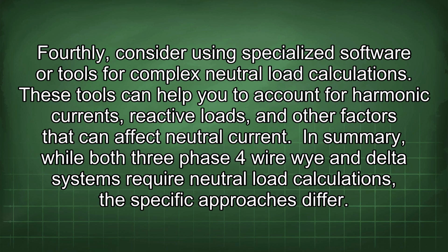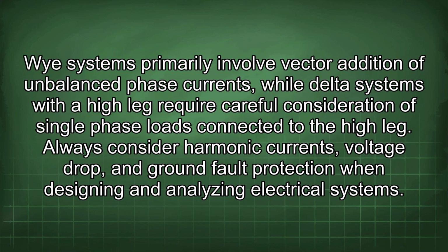In summary, while both three-phase 4-wire Y and delta systems require neutral load calculations, the specific approaches differ. Y systems primarily involve vector addition of unbalanced phase currents, while delta systems with a high leg require careful consideration of single-phase loads connected to the high leg.